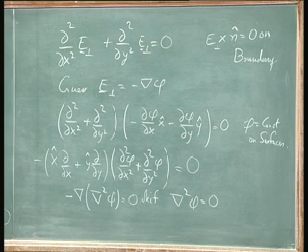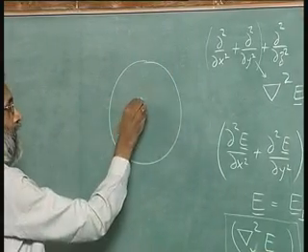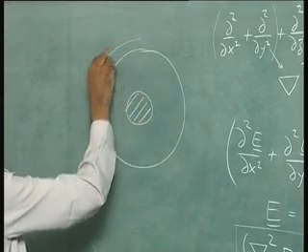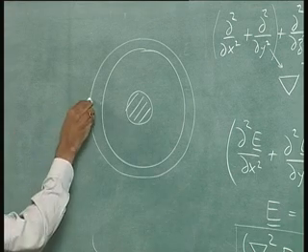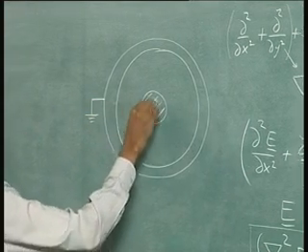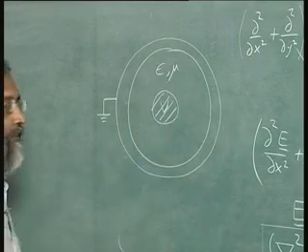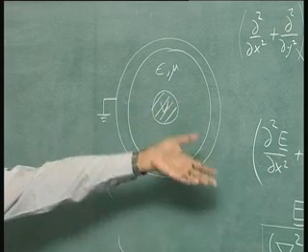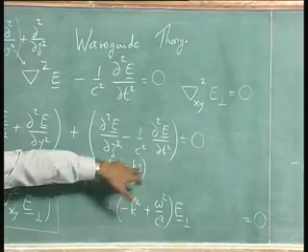Let us look for an example and see whether all of this makes sense or not. I will start with a central conductor and a metallic pipe. The outside I am going to hold at ground, inside is at some voltage V, and there is dielectric. Now, really I should not say I am holding it at a voltage V, it is going to carry a wave, which means that the voltage is not constant, voltage is a function of z.